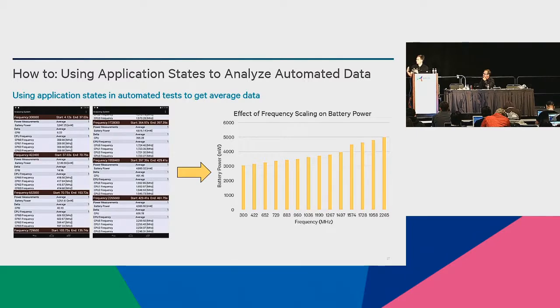If you set your processor to a specific frequency, it doesn't matter what the CPU load is. It's using the same power. So if there's no load, it's just wasting those cycles. If it's 100% load, it's using the CPU 100% efficiently, but the power stays the same. The power is only dependent on the frequency itself. But if there is no load, then the frequency is irrelevant because the CPU is just going to idle out. It's going to be clock gated and it's not going to do anything.